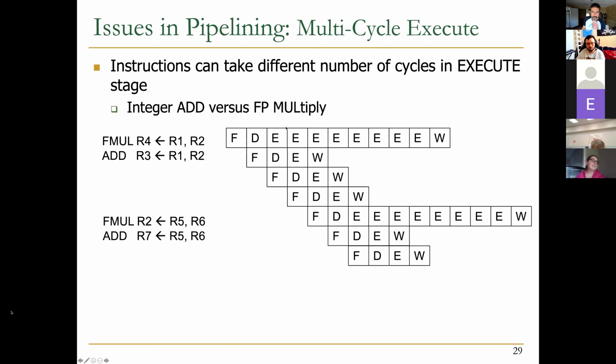The floating point requires 8 cycles for execution, and we have the other stages that you are aware of, like decoding and write back. So you see this variability for the execution, and as a result, you see this fragmented pipeline.